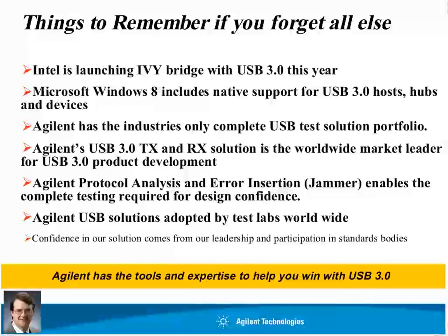The one additional thing I'd mention is all of the device classes. Getting into the higher levels, restitching together a transaction for operation is not part of the scope operation. You really need a protocol analyzer that starts looking into the operations in there, such as buffer credits going back and forth, and detecting if there's an error in that process. That's where the protocol analyzer starts following the state of the information, stitching information back together and showing reads and writes at the higher levels versus the USB protocol itself.